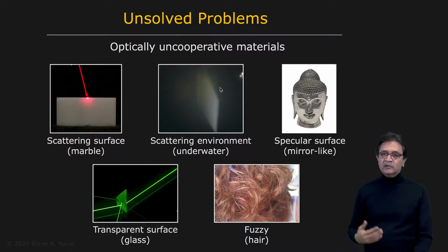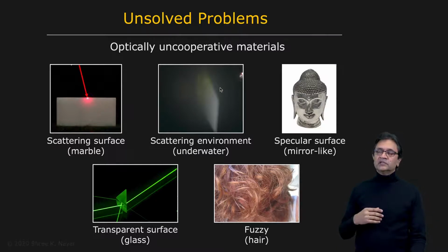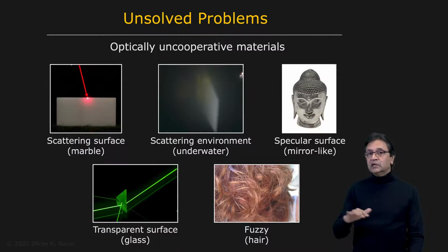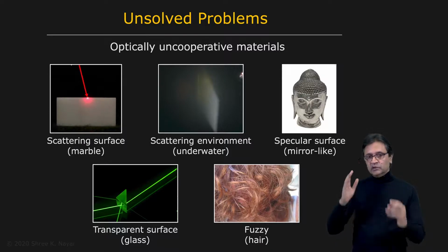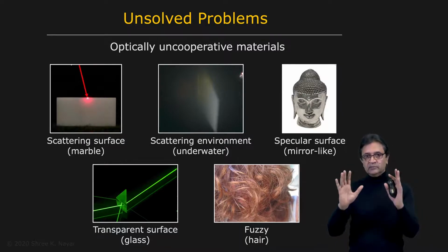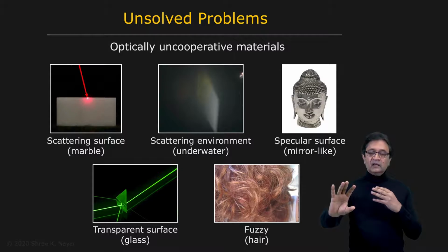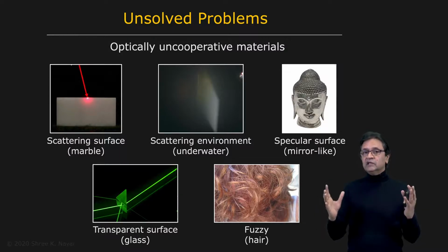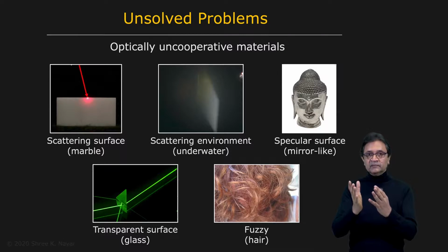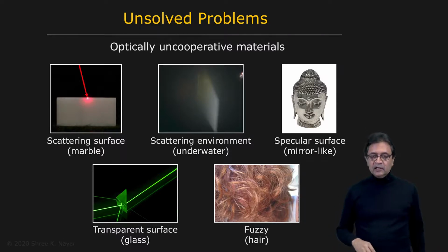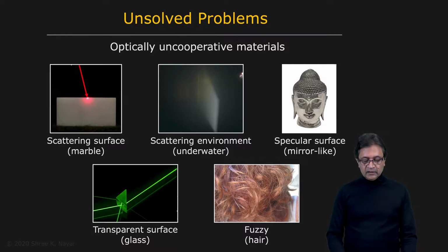And then you have participating media. Let's assume that you were talking about scanning something in the presence of fog or underwater in murky water. In these cases, when you throw out structured light, a light pattern, the pattern itself is going to decay rapidly as it travels through the participating media. And in addition to that, the medium itself begins to glow because of this light. So these are very hard measurement problems, and structured light underwater, for instance, has many interesting challenges.